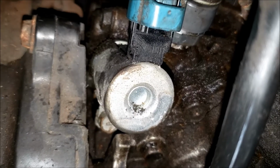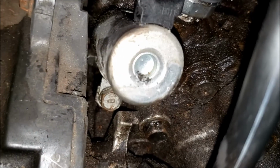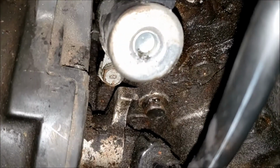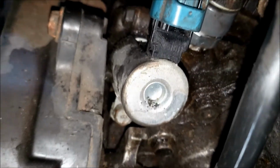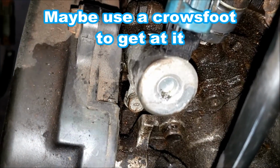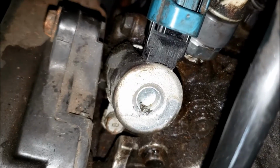And actually, I got to correct myself, because looking back over at the Bank 1 driver's side, you can see that lower 10mm bolt is partially blocked by the cam position sensor mounting bracket, I guess that is. So I'm not putting one of these in right now. I just wanted to show you guys what's involved, but that looks like it might be a little tougher to get to, and I'm sure if you do a quick Google search, you can find out if you can slip and slide that or not. Can't really tell you for sure without removing it though. And I think that wraps us up.